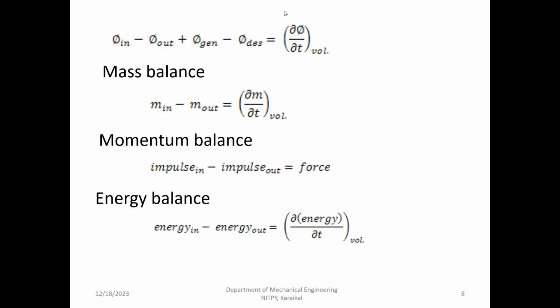Burning of fuel, again, we are going to say I have fuel and oxidizer coming in with certain enthalpy. It's going to burn. The exhaust products will go out with some other enthalpy. That's going to be a difference in enthalpy, and that difference is equal to the heat produced. The heat is going to be in the form of temperature, so that's going to be m Cp delta T. So I have enthalpy as input energy, enthalpy as output energy, and heat as another output energy. So enthalpy in must be equal to heat plus enthalpy out. It doesn't come in abruptly, so that is not destroyed completely.